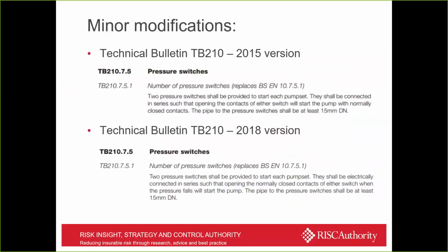TB210, 15 and 18. Again, a clarification. The contacts of either switch will start the pump or normally closed contacts. This has been changed to normally closed contacts of either switch when the pressure falls. We have just reworded this for clarification. There is still no change technically to TB210 in the latest version.